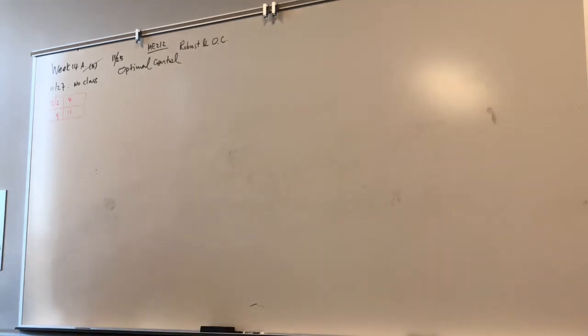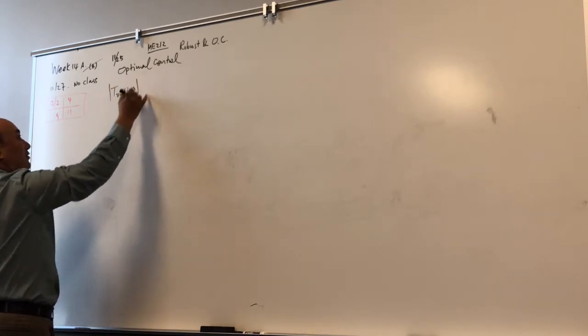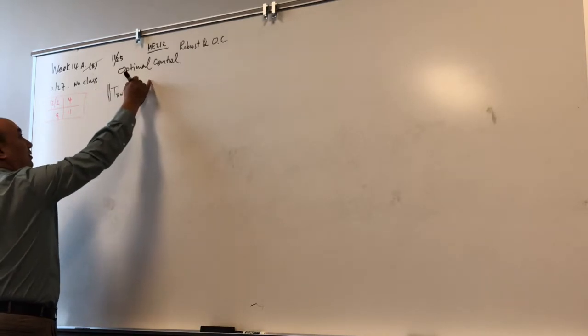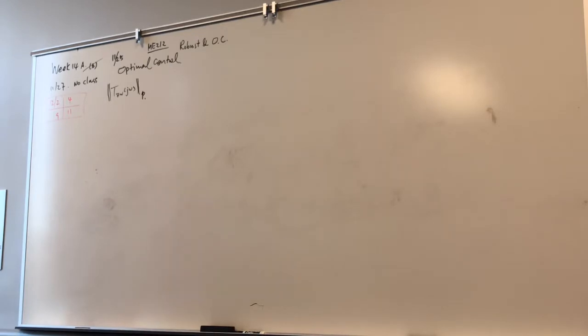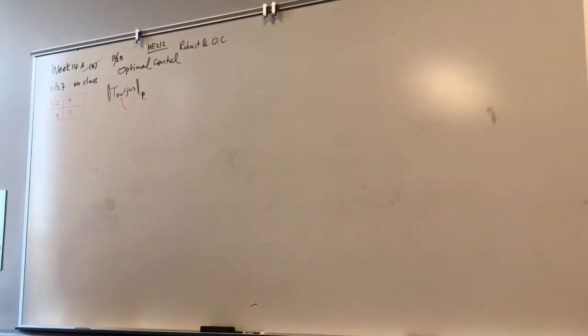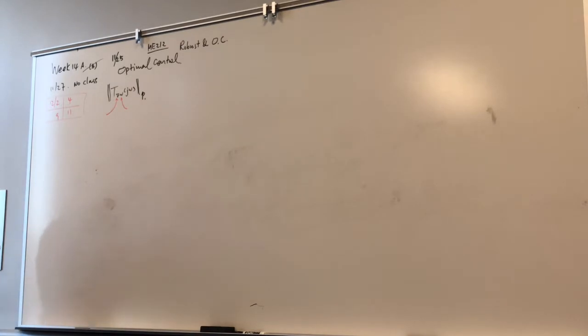It is optimal in the sense of T_zw(jω) norm, either in 2 norm or in H infinity norm. That's from the in and out performance index. Remember, we use Z and W. W is introduced to make an assessment of the performance variable Z, so T_zw.